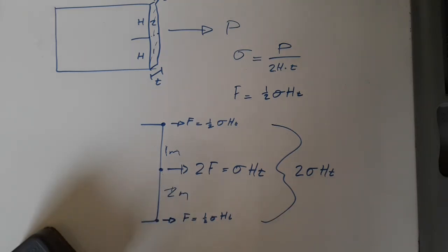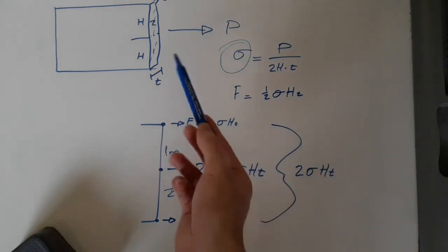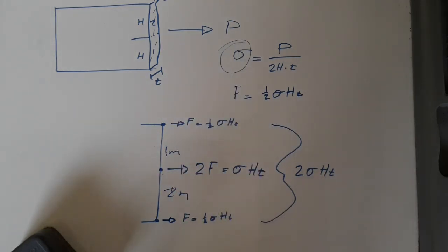It would be the same thing, where both elements should have the same stress as the overall stress caused by the total force. Once you have that stress, you can work out the elemental force and then distribute that between the two nodes. Then just remember that when two elements share a node, that node would have a force from both elements, and you would have to add those two together.